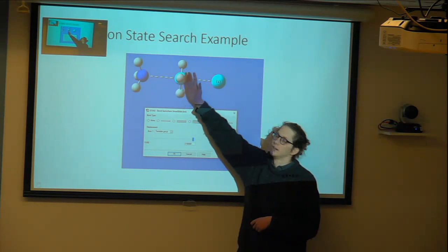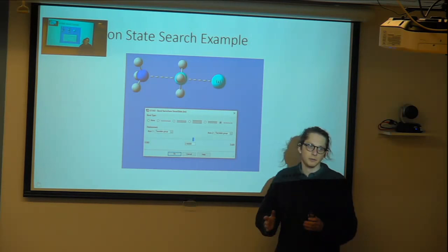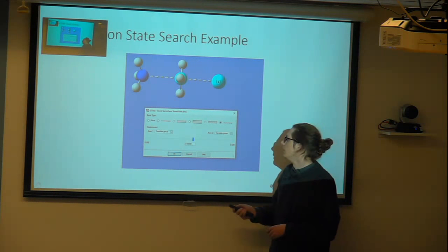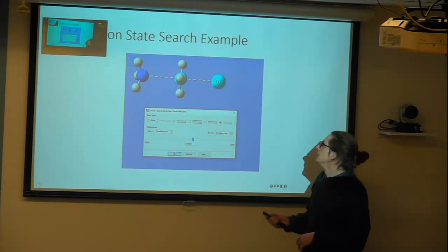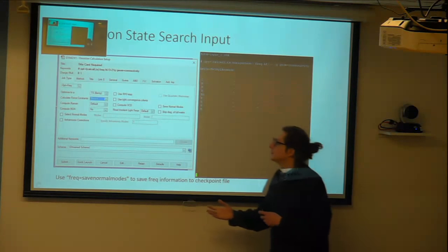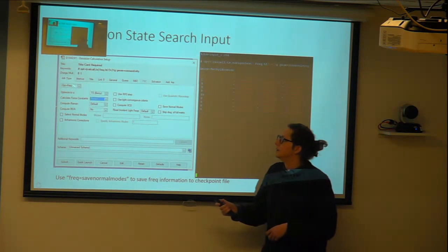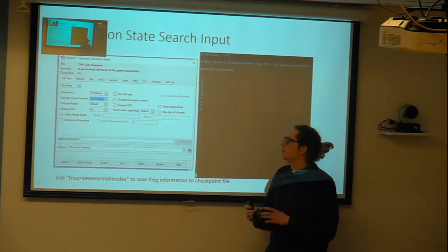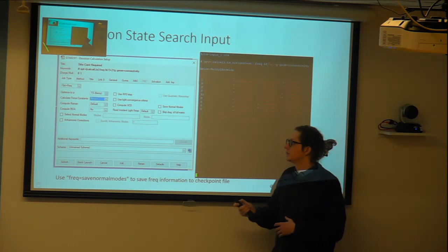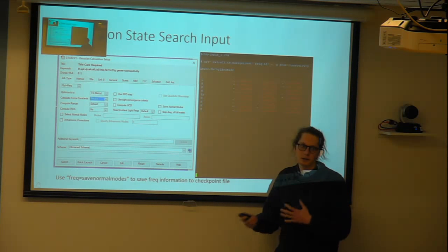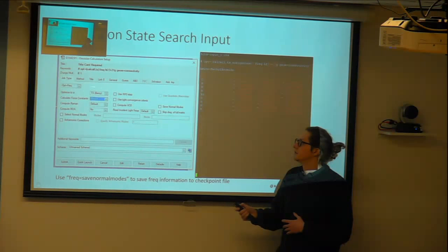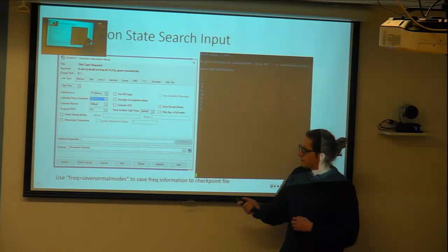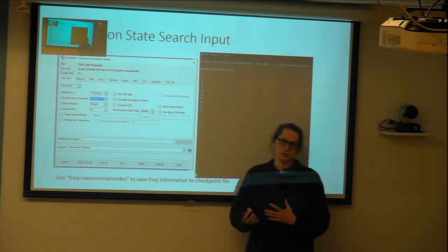And as you can see, I have my hydrogens and carbons all in one place. So after you set up your bond lengths, you need to set up your calculation. For a job type, you want to select optimization plus frequency. But this will not optimize to a transition state unless you tell it specifically to optimize to a transition state. You can select that. Next thing that you're probably going to want to do is calculate force constants.